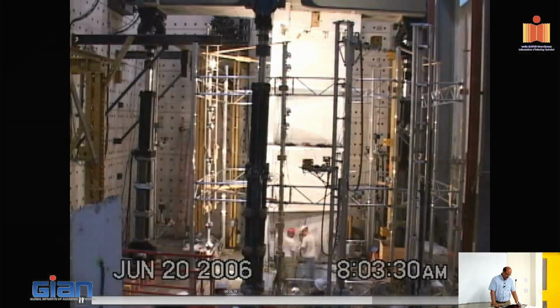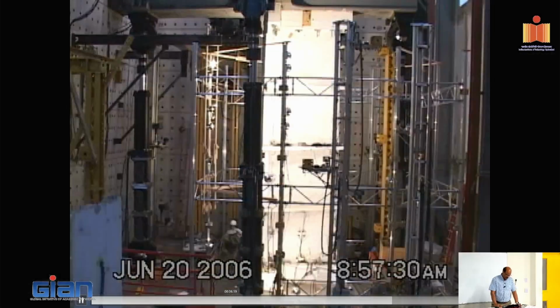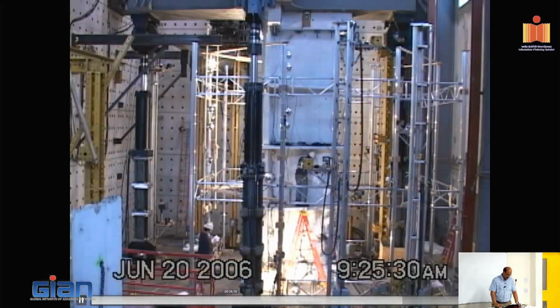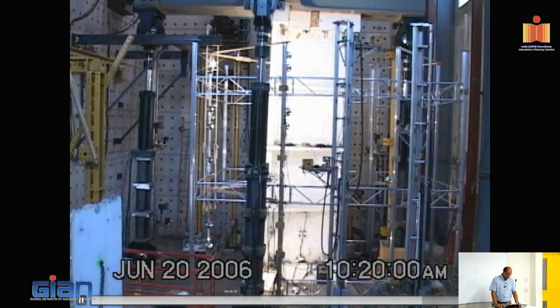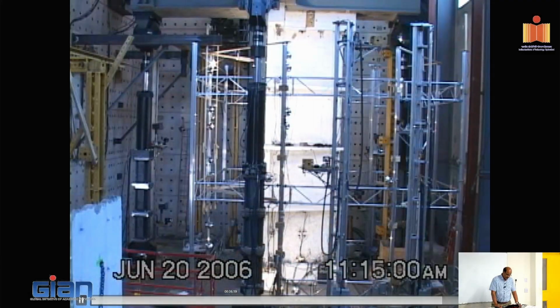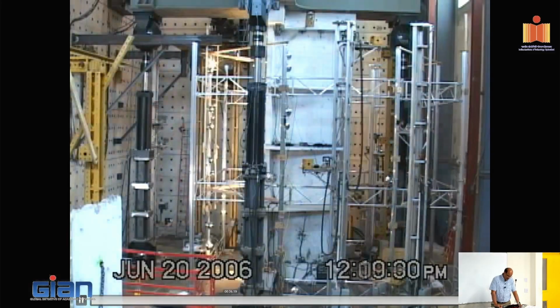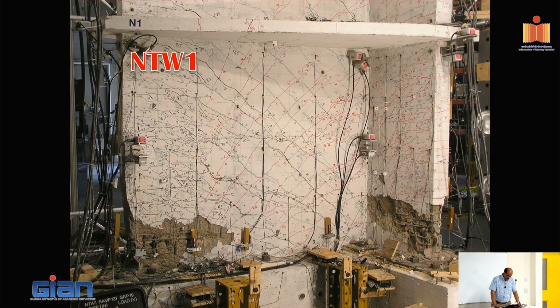Yeah, I want you to observe how much you can move these things while the system is pretty stable. You could see again, it's a T-wall, which is common in buildings, and the damage is primarily happening at the base where the plastic action is taking place because it was tested as a cantilever. I probably have some pictures showing this, so here's one direction. Again, I want you to observe what the plastification in a cast-in-place structure would look like.